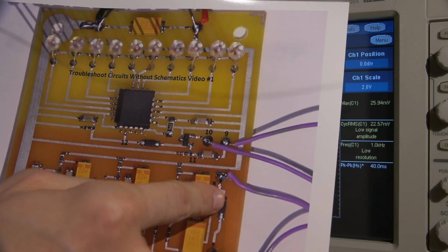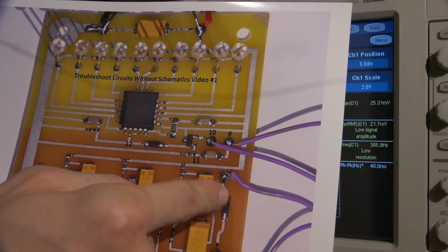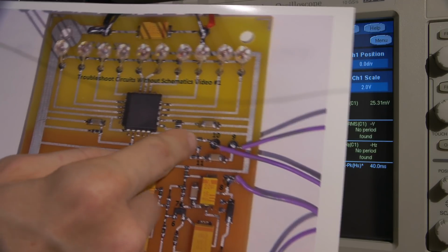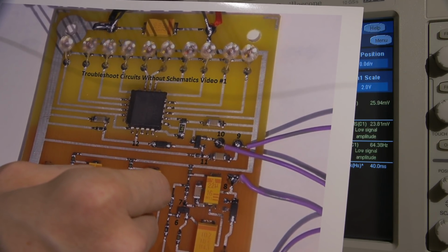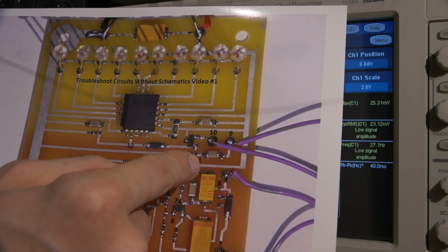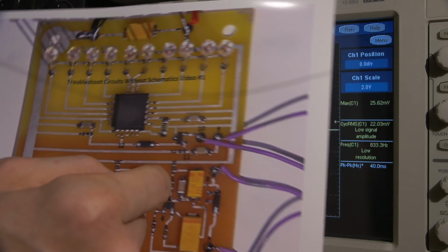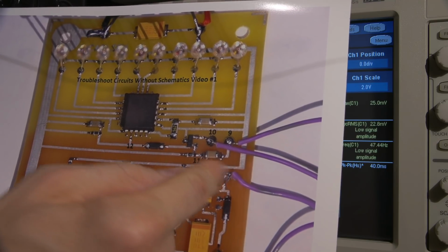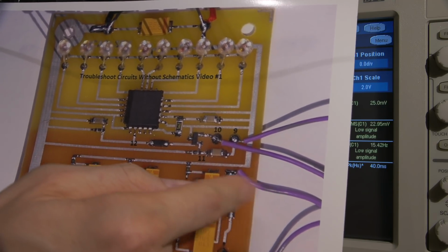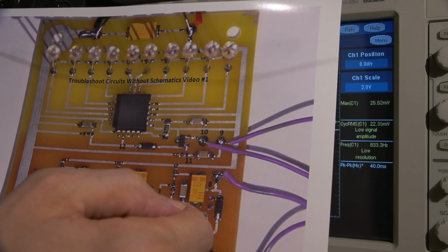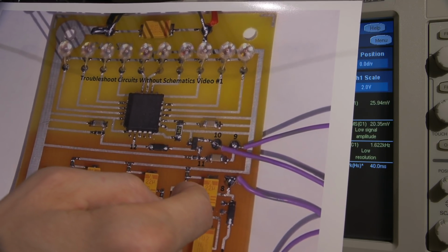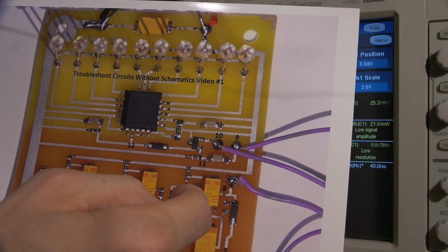The function of this diode here is just to step up gain, a bit of pre-rectification for the intensified position, just to get the gains a little bit closer, so we have a little more gain in the actual intensified position. That's really just what this diode is doing, pre-rectification, giving us some pulsing DC at that point, trimming the bottom portion of the sine wave is what I should be saying. That's really all that's happening in this circuit.